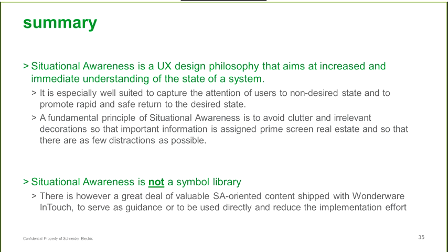When we summarize situational awareness, I would like to point out that it is not just a symbol library. The important part here is it's a design philosophy. If we want to increase operator awareness, we should not fill the screens with large symbols that don't make any sense to the operators. And also that we create the displays according to who's logged in. If we have an operator, he might have one need, and if we have a maintenance guy logging in, then the pages should look a bit different, and that will cover his need.